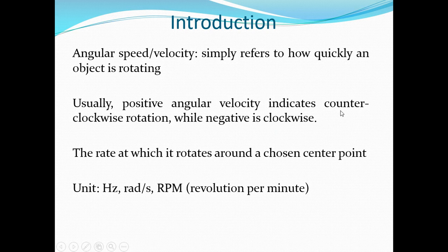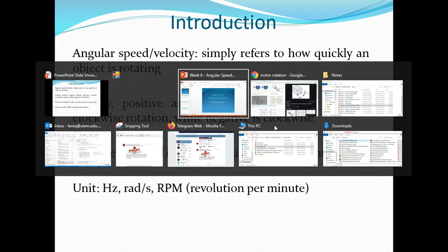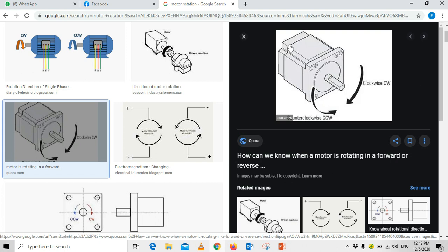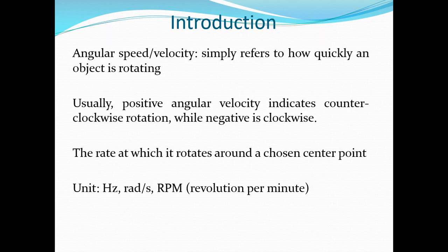Okay, you know how to measure counterclockwise or clockwise, where you want to check from the front or the back of the motor. Actually, to check it, you need to go from this one. Okay, this is the motor. Here is the front. Here is the back. You check from the front. This is your eye here. You check from here. Right is clockwise and turning left is counterclockwise. This is how you measure the rotation of the motor, right?